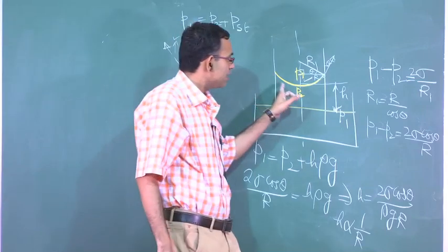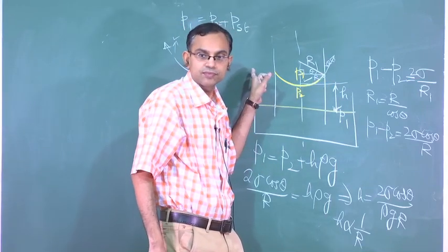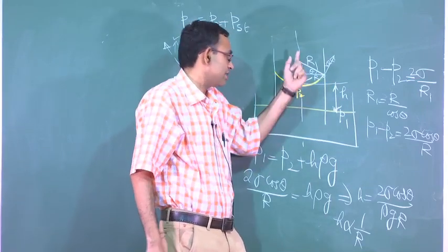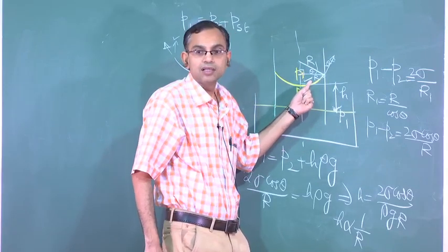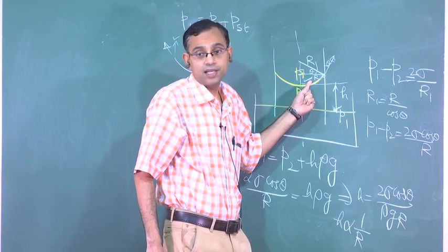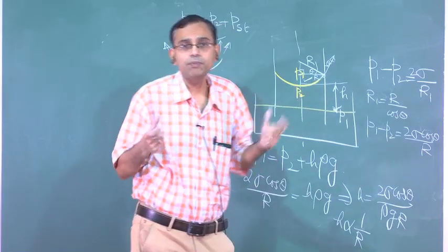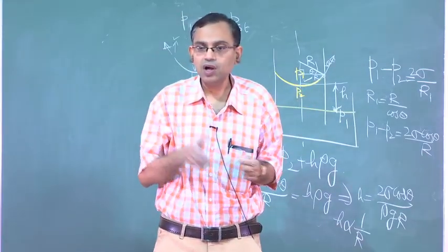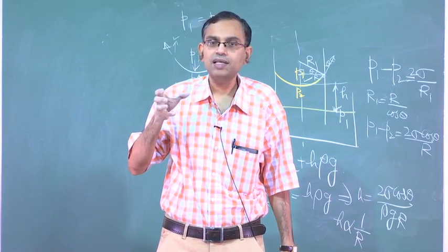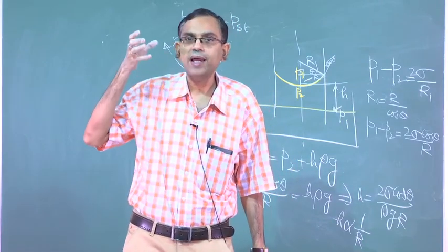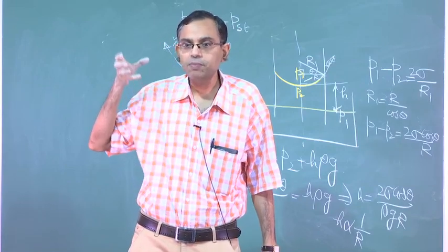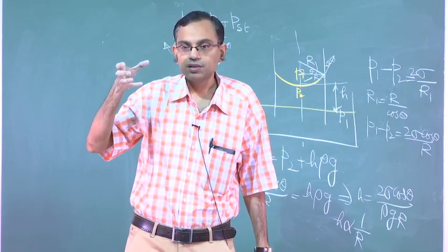So, this capillary rise is important as a formula, but it is also important to understand that this is just the description of statics. How fast or how quickly this capillary is being filled is called capillary filling dynamics. And why it is important in biomicrofluidics is because you may have, let us say, a micro needle, or a medical diagnostic device through which a blood sample is moving.